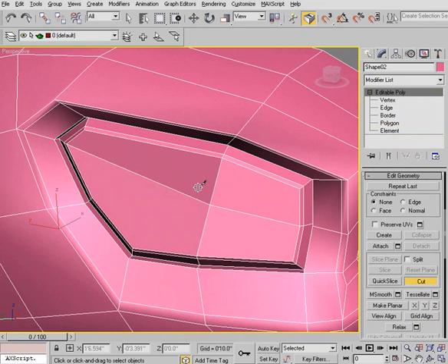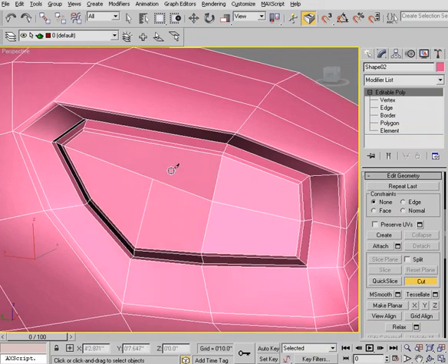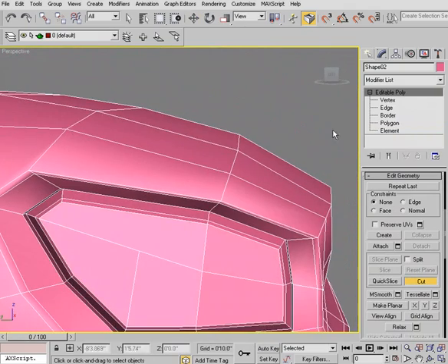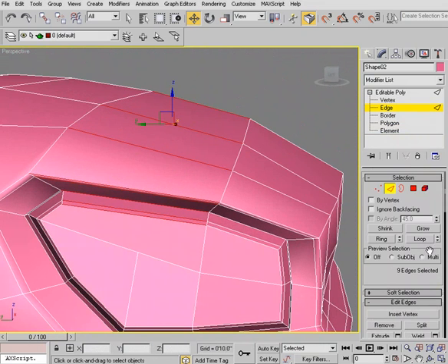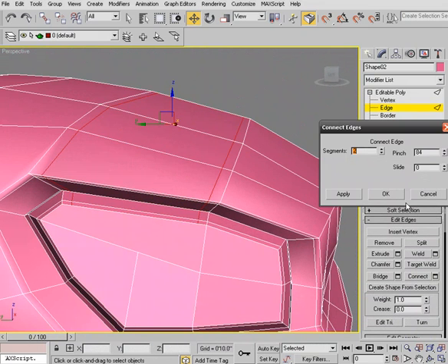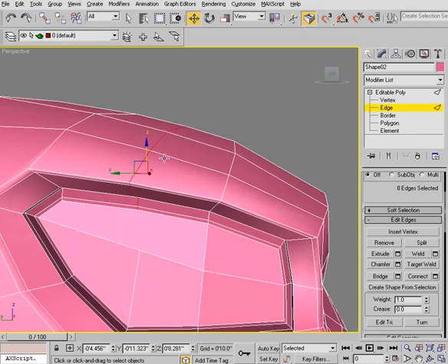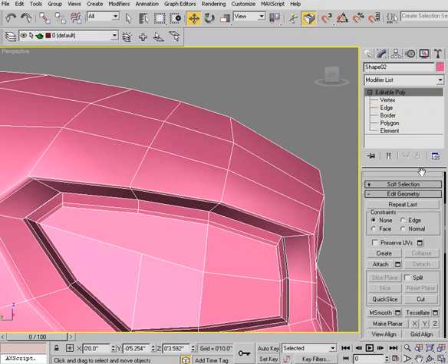Up to there, and then we can start to look at this and say, I want to come in and draw this across. Now, in this case, we don't have anywhere to put this, so you can go ahead and add another edge loop right up here. So even now, working with our polygons, we can still add additional geometry here. I'm going to take the pinch down, and slide that about halfway, and then you want to modify that curve just a little bit, and then go ahead and cut that across.